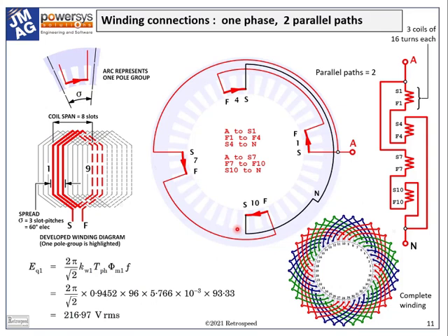Each group comprises 3 lapped coils, and this defines the so-called phase spread as 3 slot pitches, which is 3 times 10 mechanical degrees, or 3 times 20 equals 60 electrical degrees, a common configuration. In the induction motor, the number of turns per coil was 17.